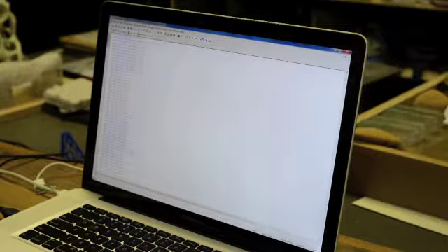So this is the actual G code, all these X, Y, Z values telling it where to go. And over here, you have XY and then IJ, this is telling you that it's doing a curve somewhere. So down here at this line, it's going to start to turn. Same here, that's what the IJ is.